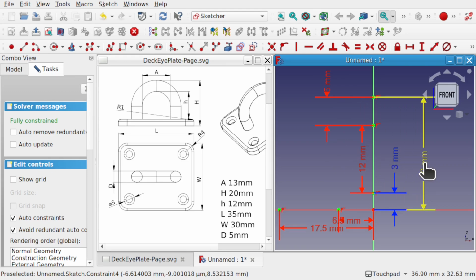So what we've done is we've created a number of dimensions in here and roughed out whereabouts all these will go. This is important because the workflow we're looking at for the part design, we have to make each part connect as we go along. So we create the base, and then for this rotate here, we need to first make a pad and then a rotate. We're going to be showing you how to do that in a moment.